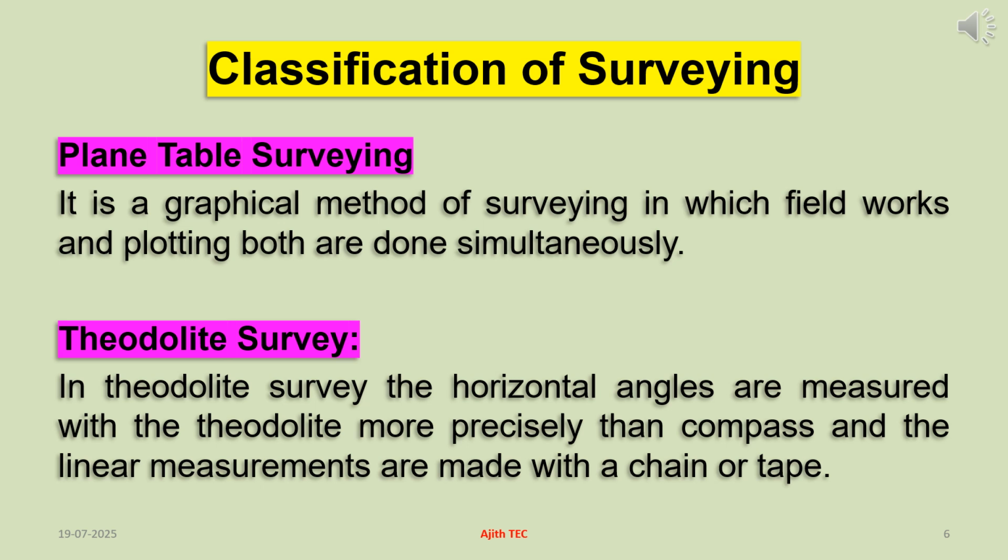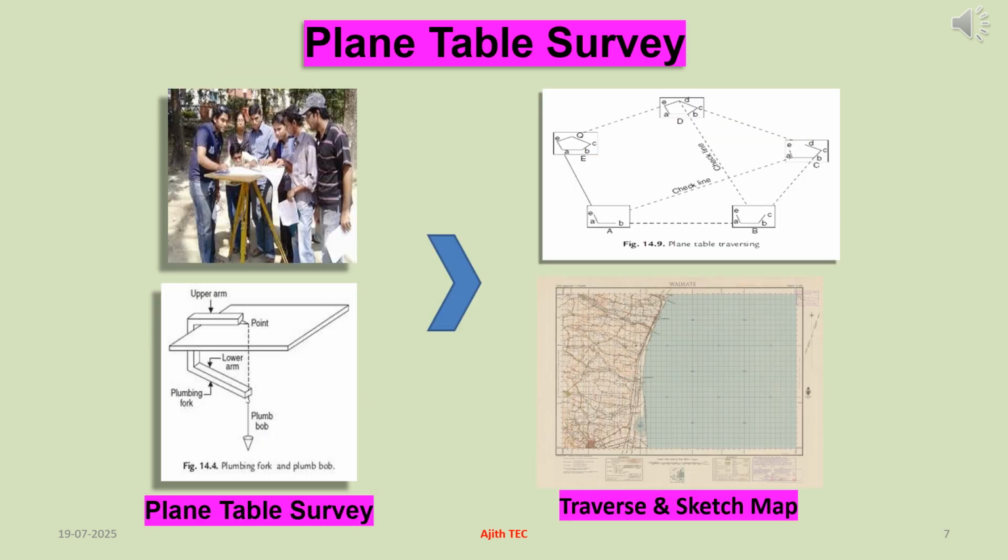A theodolite is an optical instrument that measures horizontal and vertical angles between 2 points. Distance between traverse points is measured with the help of chain. Required detail points are picked with the help of chain and tape using offset method. It shows how to perform plane table surveying with the help of plane table, chain or tape. Then required measurements are taken from all detail points and a small-scale map is prepared according to ground features.